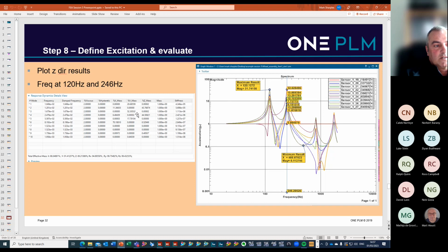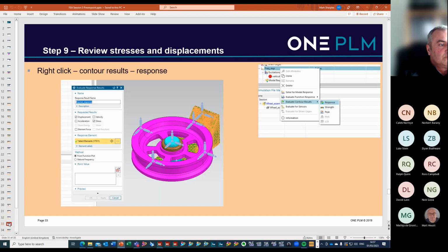So here again, you can see this one, the 247, is a very dominant mode in the Z direction. Therefore, when I excite it in Z, then again, you'll see that it's causing me a resonance or giving me a peak. So you can relate what you get with effective mass to the response that you get from your structure. And then you could go ahead and calculate the physical displacement and response. So let me show you how you would do that.